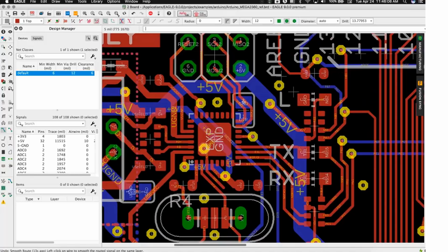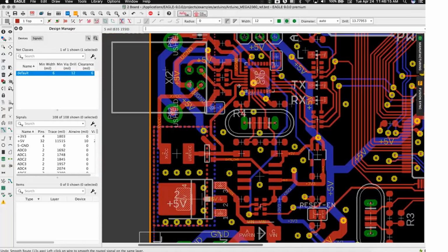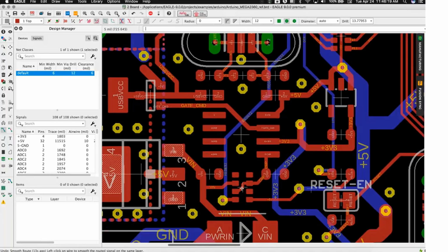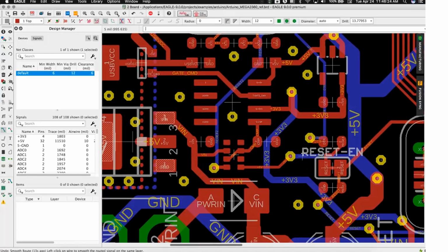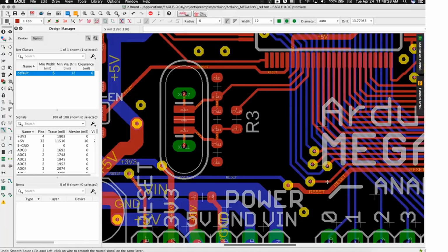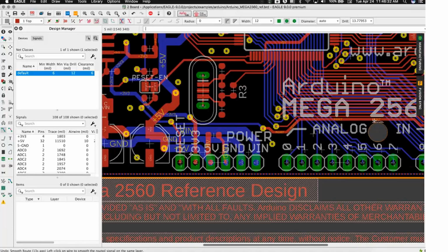I just wanted to add, Matt, with the combination of the quick route and the rip-up tools, what I've noticed is that if you have a workflow between Eagle and Fusion 360, when the mechanical engineer moves those parts and you get it back in Eagle, you know that your traces are totally out of whack. So it makes it much easier for you to rip them up and quick route it before you shoot it back to the mechanical engineer. Yeah, absolutely.